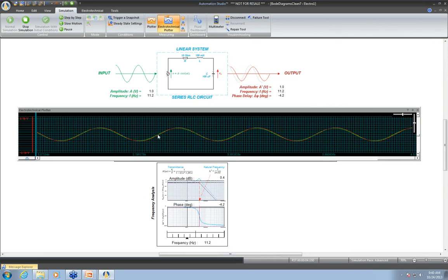Right now you can see here both input, which is green color, and the output are of the same phase, and there is not much difference between the amplitude, as well as there is not much difference in the phase lag as well. So for example, if I'm going to adjust my frequencies here, you can automatically see when it goes, there is a simple phase lag appearing at 37.9 Hertz. So if I just keep on increasing, the output and the input has a phase lag of 150 degrees, and the amplitude also changes. When I further increase it more, there is a cutoff frequency by the filter. So you can see here the output signal has really less curves over here.